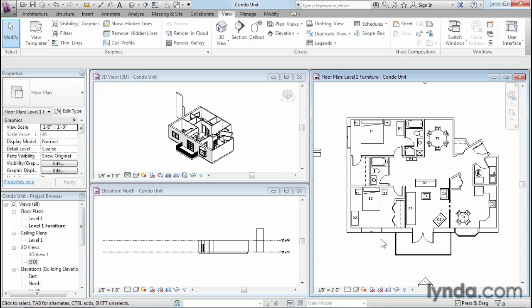If you want to select more than one object, the easiest way that you can do that is to use either a window or a crossing selection. Now, both of these are very similar to the counterparts in AutoCAD. The difference is the way that you execute the windows and crossings. So in AutoCAD, you would go click and then click to create a window, but you'll notice here in Revit, it doesn't do anything when I do that. In Revit, you click and drag to get a window selection. In all other ways, it behaves exactly the same way, though.